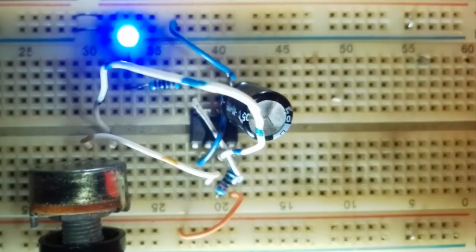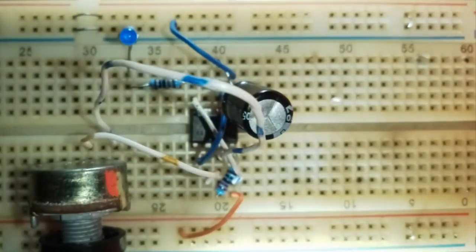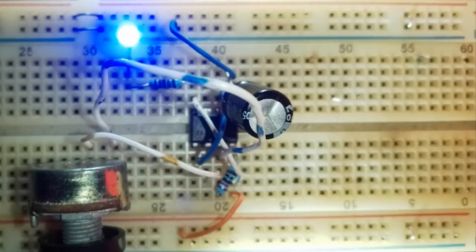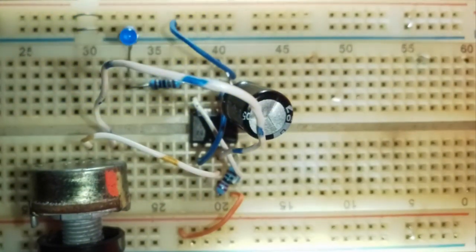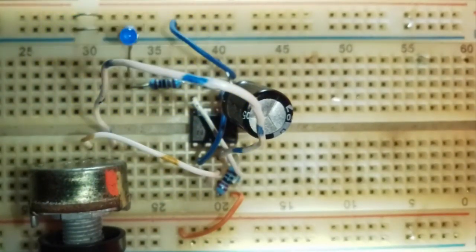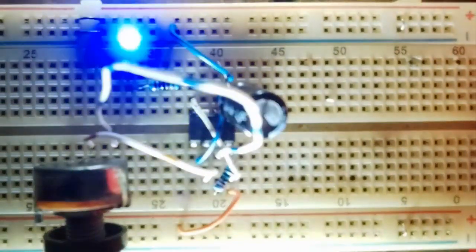Power the board and turn the knob to see how the flashing rate of the LED changes with each turn in either direction. The explanation once again comes to the amount of charging current passing through to C1. Higher resistance leads to less current flowing through, which results in a lower charging rate for the capacitor. That causes the LED to flash much slower if R2 value is increased. The reverse is also true.